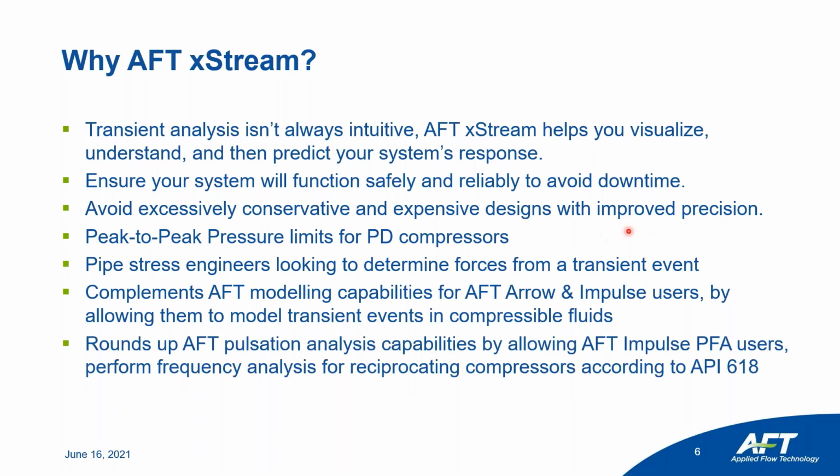It rounds out AFT pulsation analysis capabilities by allowing AFT Impulse PFA users to perform frequency analysis for reciprocating compressors according to API 618. And finally, and very important, it will allow you to comply with codes.